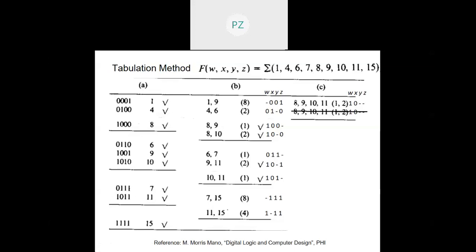Second, so what about don't care? If there is a don't care condition, there are a few terms which are don't care. Then how do you do them? What I'll suggest, that from the very beginning, keep treating the don't cares as if they are min terms.